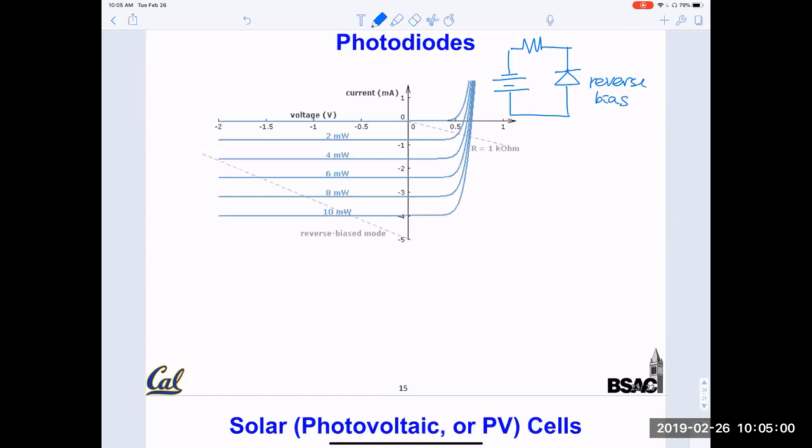And how does the IV curve change when light shines on it? When light shines on it, it will generate a current. Without getting into detailed device physics, in reverse bias there's no current flowing, but there's a huge field developed in the junction. When you create an electron-hole pair, the photon knocks out one electron from the bound atomic bonds between silicons. So it creates one electron and one hole.